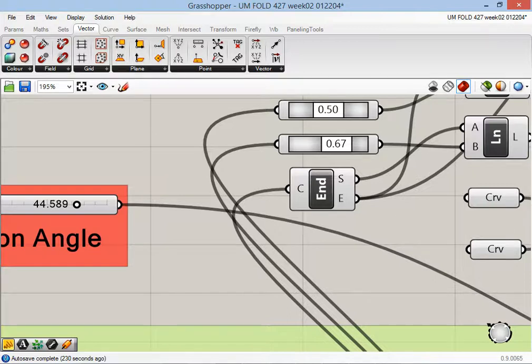If this thing is laying like this, I can move it, but it's still going to lay like that. The piece won't be able to be flipped. With orient, we can move it there, but then also lay it, flip it, based off of a plane. So orient is going to be a much more powerful manipulation tool, all right?